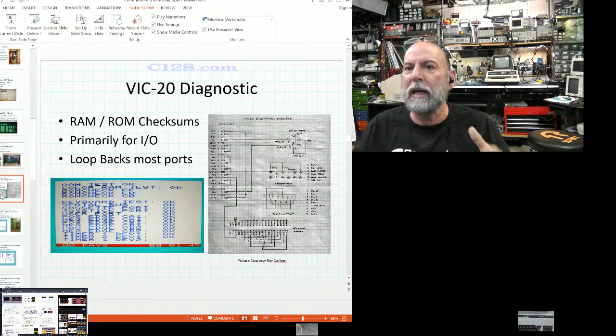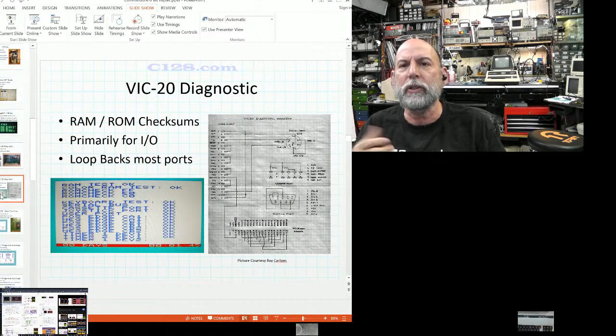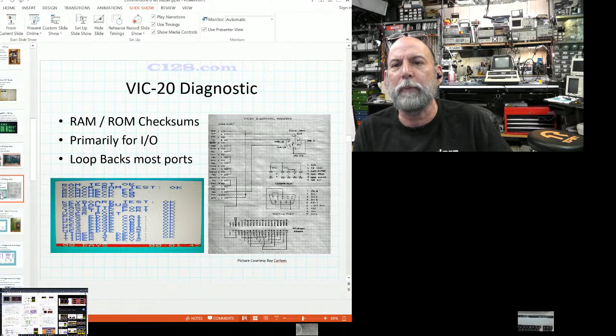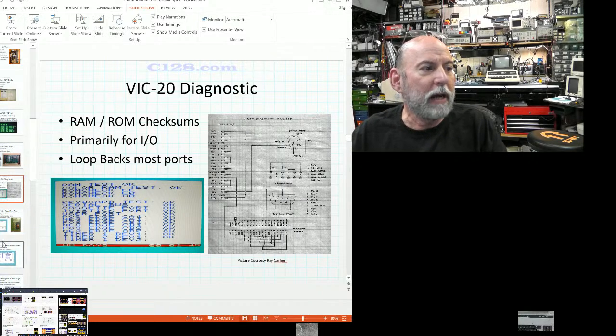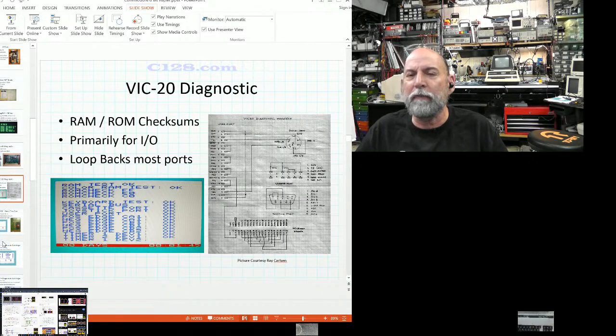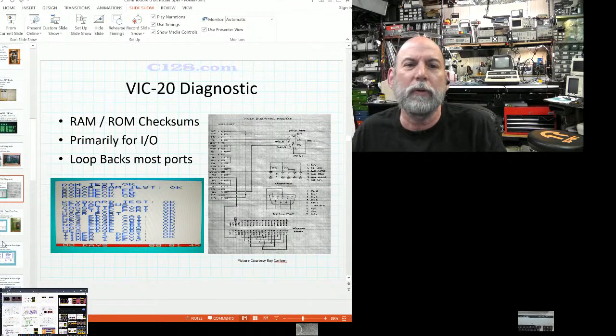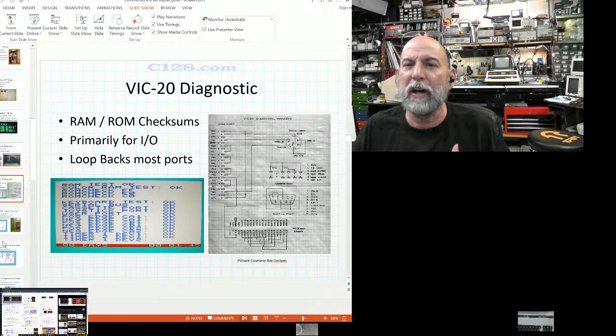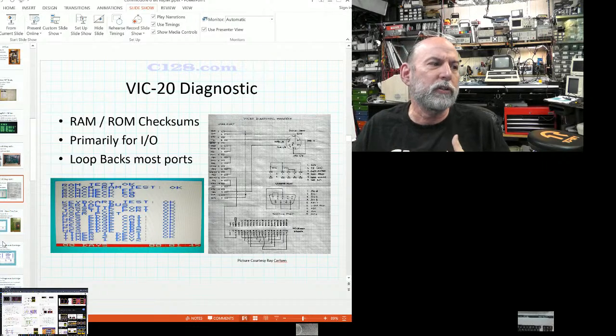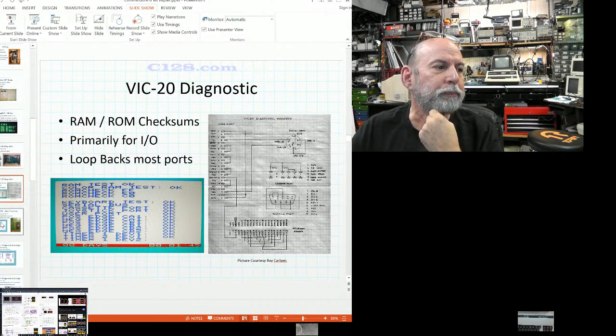We simply clamped it down, powered it up, and tried to have the diagnostics kick on as much of the circuitry as we could. Okay. So it was basically a dead or no dead detector. Then you would do some swapping, and you would swap the VIC chip and the processor, without even thinking about it. Now, in production, they would be careful about what they swapped so that they weren't throwing away as many chips as I did in R&D. It's a completely different environment where we're trying to reduce our scrap as much as possible.